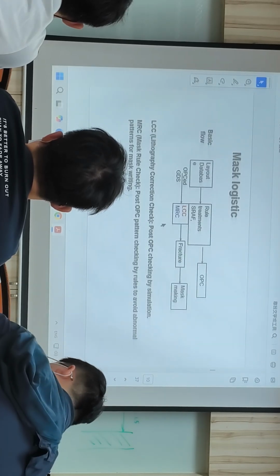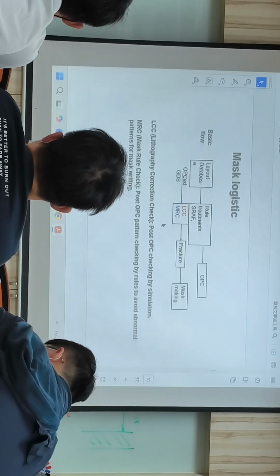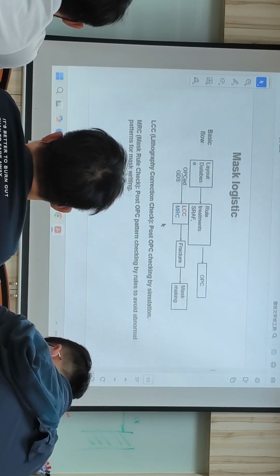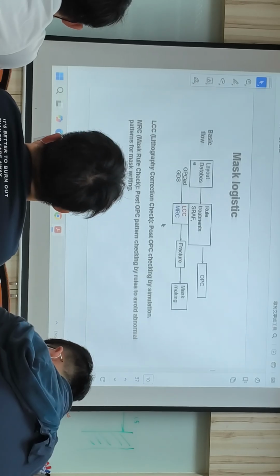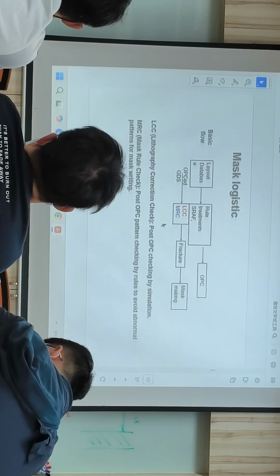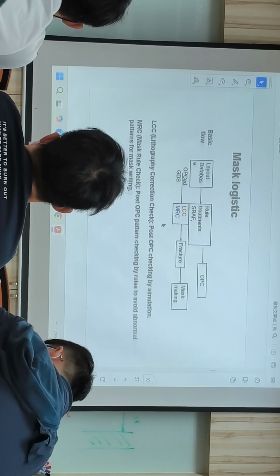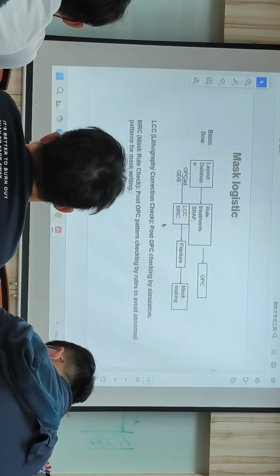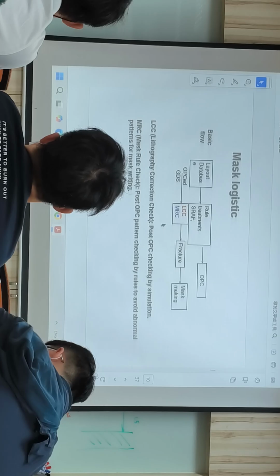Initially, it should be a straight line, and then they probably do it in two segments, and the gap is so small, maybe it's only 1 nanometer. If you don't look very closely, you think it's connected, but it's not. So before doing the OPC, they need to do this kind of dummy check, to make sure all the lines are connected and without anything funny like this.